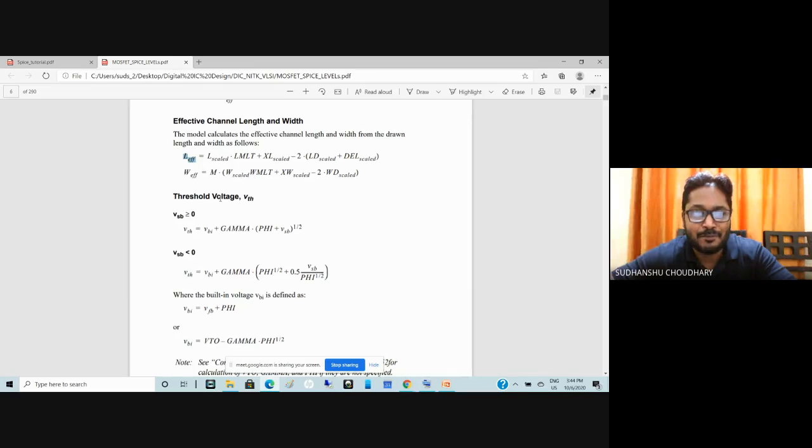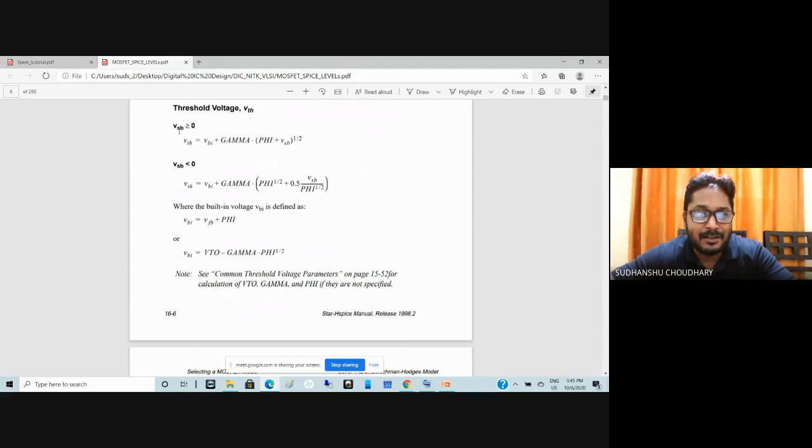Maybe I'll also give you a brief introduction on the device characteristics, device dimensions and device geometry. Then I think you will understand these parameters better. Then, to include the body bias effect, you have substrate-to-bulk or source-to-bulk biases. These are also considered to calculate the threshold voltage, yeah?